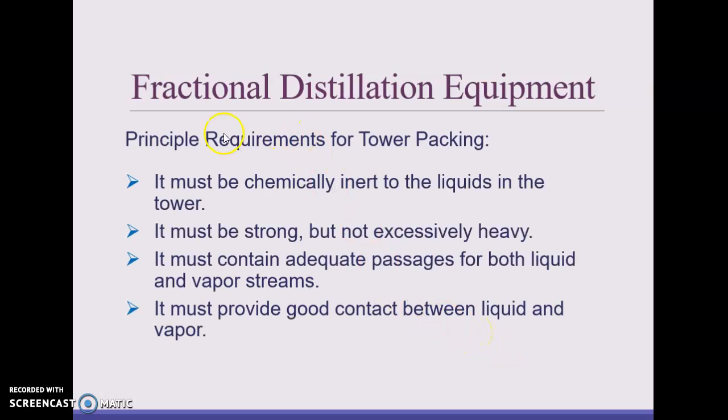Okay. So some principal requirements for tower packing. It must be chemically inert to the liquids of the tower. It must be strong, not excessively heavy, and must contain adequate passage for the streams. And it must provide good contact between liquid and vapor and be reasonable in cost.